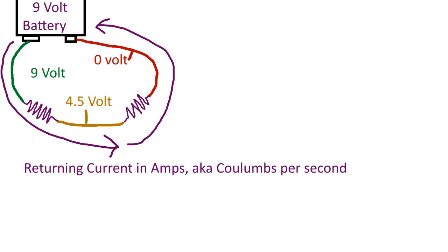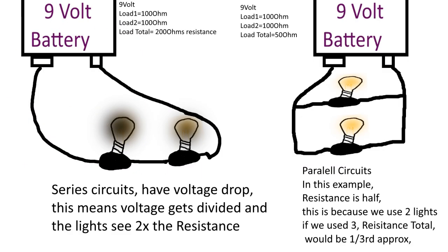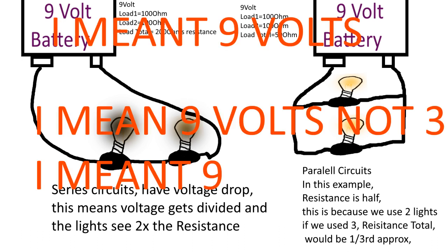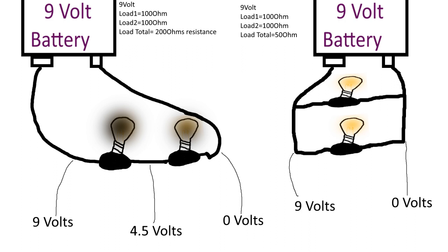So Kirchhoff's voltage law means that in a series circuit, in that light bulb circuit, I'll draw it. Here it is right here. As you can see, the one light bulb circuit right here is at full brightness with the 3 volts across it. But in the other light bulb circuit that I'm displaying under it, you can see it has 2 light bulbs, and since we have 3 volts across the 2 light bulbs, it divides, and each light bulb gets 1.5 volts.